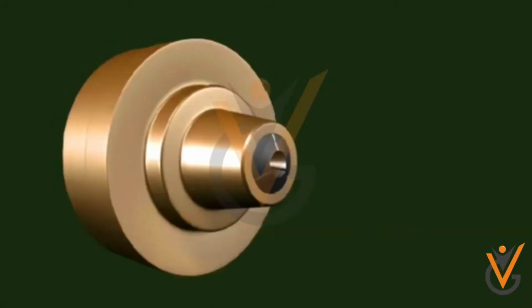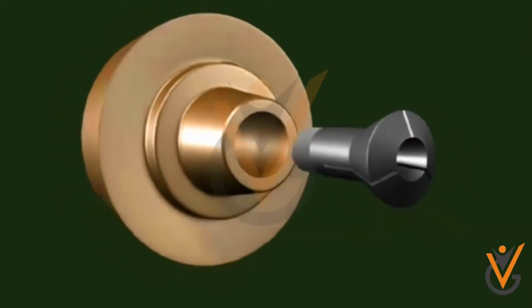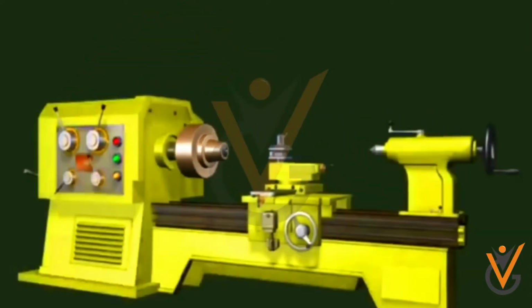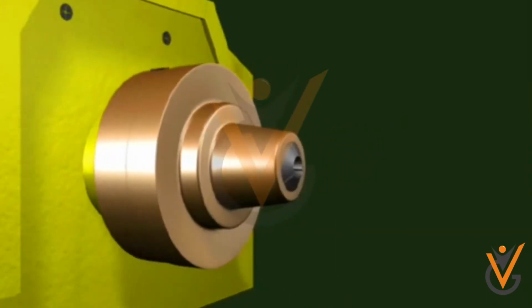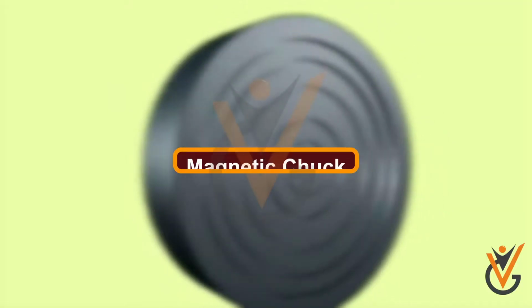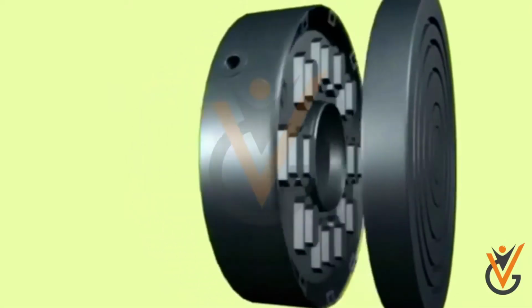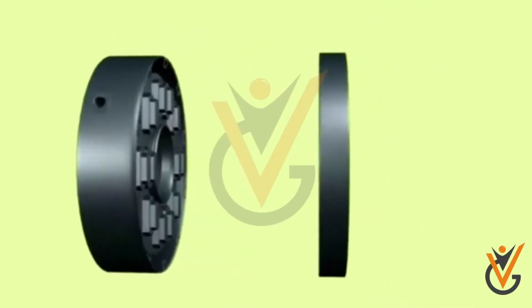Collet chuck. It is mostly used in the places where production work is required, such as in capstan lathe or automats. It is used for holding the bars of small sizes below 63 mm. Magnetic chuck. They are of permanent magnet type, and are electrically operated. In lathe, it does not have widespread use.